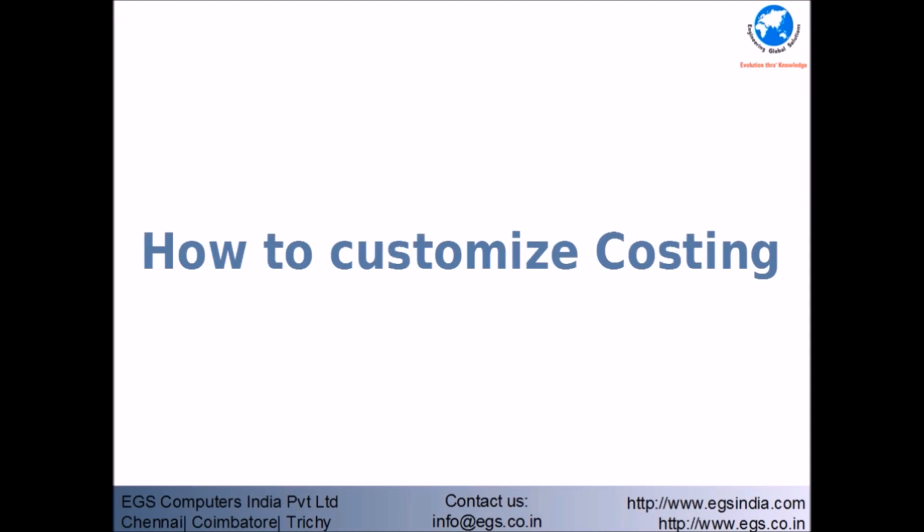How to customize costing. Customize and save the default templates to provide your own manufacturing, labor and material costs. Override the calculated cost and material cost. Add discounts and markups. Change quantities. Add custom operations. Adjust costing reports to display quote, customer and company information. Assign a custom cost to the body of a multi-body part. Set the machined part costing option to recognize removed material as a volume feature. Simplify the cost estimate to minimize template dependency.